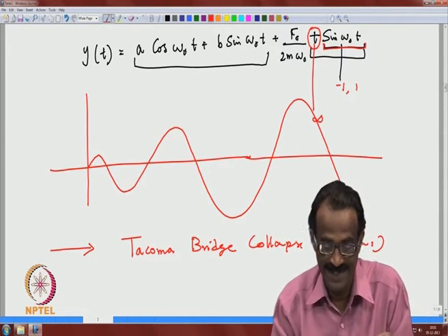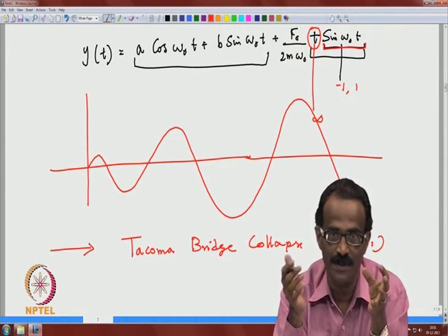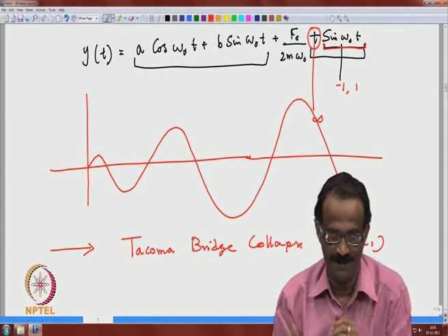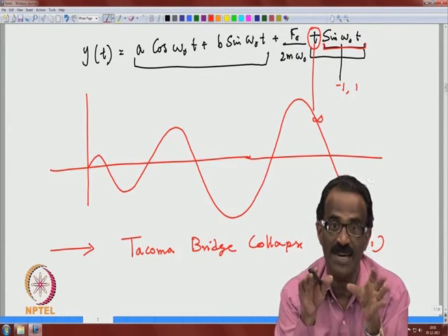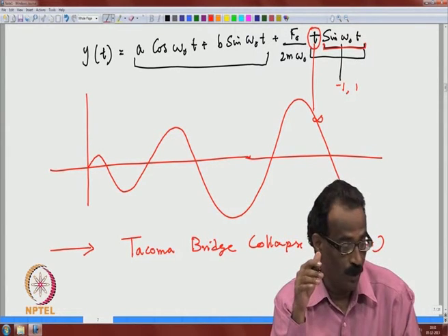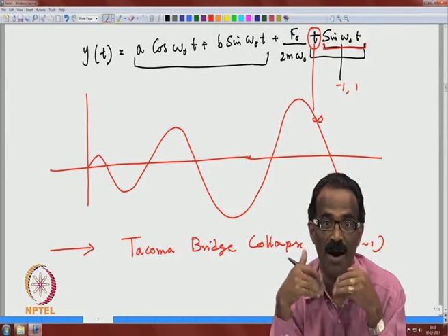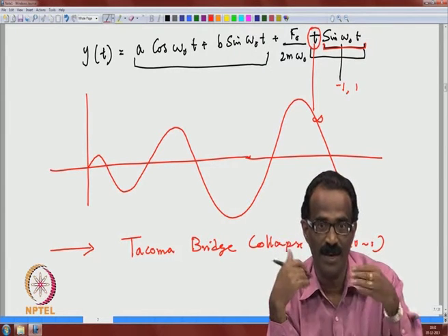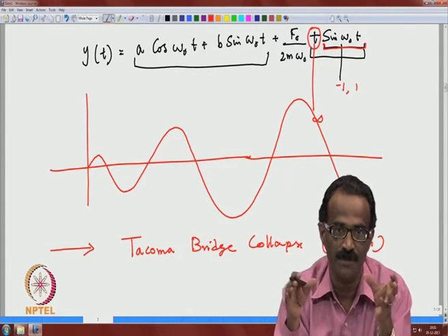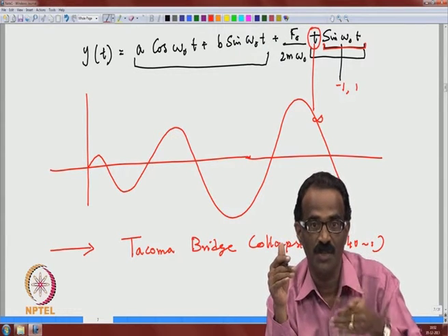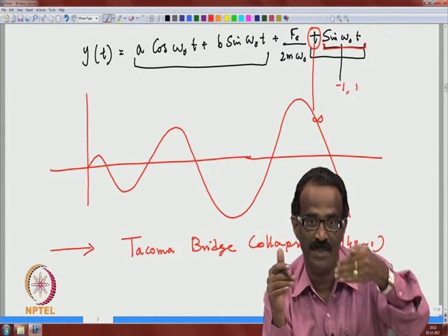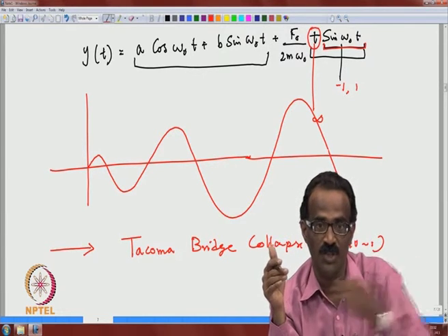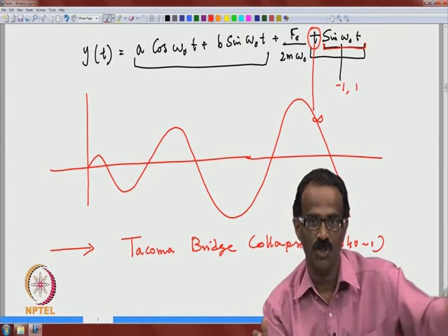The interesting tale of that one is that nobody died in that huge disaster except a dog. And this is also the reason, probably you have seen, that in military or army marching through a bridge, the army does not march like how we walk, where we create different types of vibration. Army marching is with a particular frequency and it will be very high. That is why when the army marches through the bridge, they will not allow continuous marching.